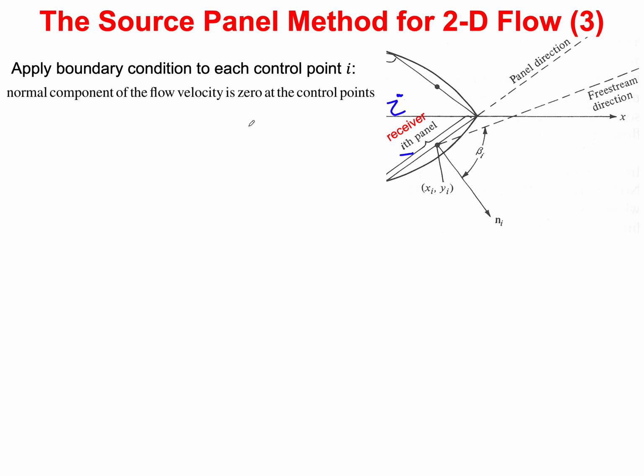So now we need to apply the boundary condition, and the boundary condition will be, as we said, that we want this to be a streamline, so the velocity perpendicular, in the unit n vector direction, is going to be 0. The velocity is going to be 0, or d phi dn is 0, as we have seen earlier. So we're talking about the same thing, v dot n.